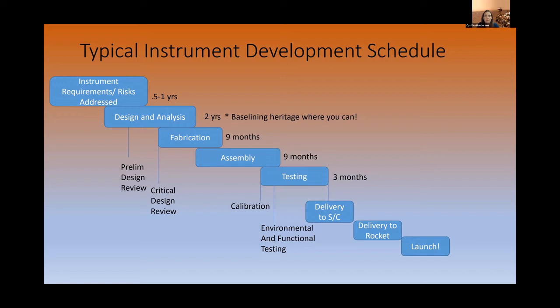During this part of development, all the design and analysis is critically reviewed by very tough NASA review panels, and then we start having parts fabricated. Every part that gets fabricated requires a release drawing with any critical subsystem lead engineer and QA weighing in. So we're not just making the decisions for ourselves as the mechanical engineers. We have to have sign-offs from thermal engineers, electrical engineers, scientists, you name it. Nothing goes unchecked.